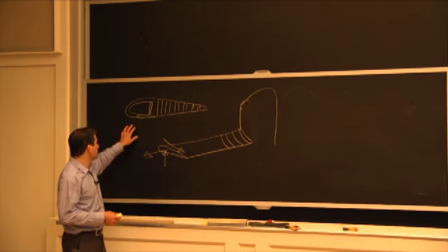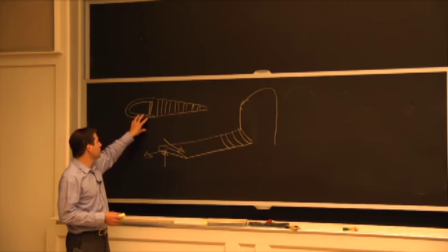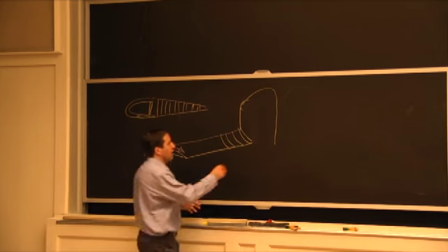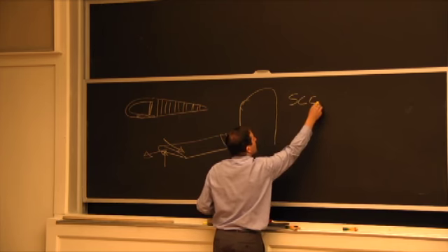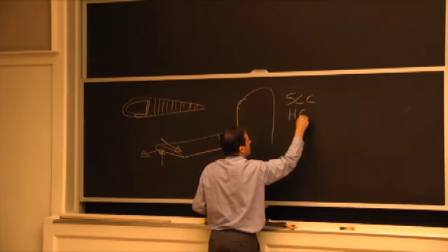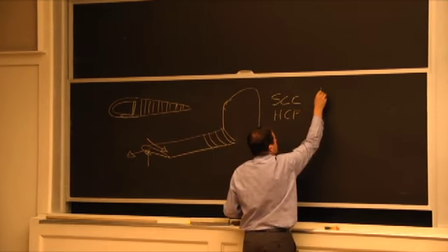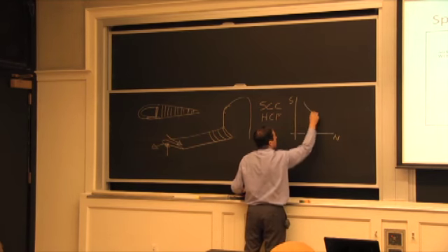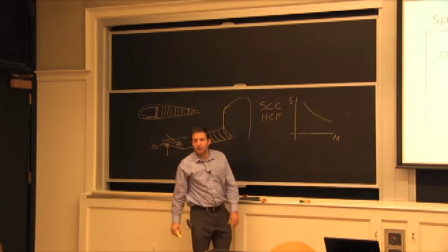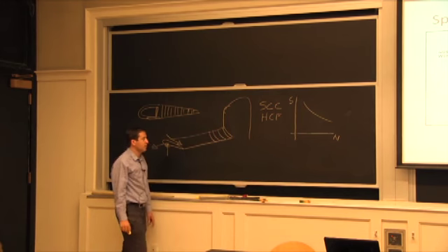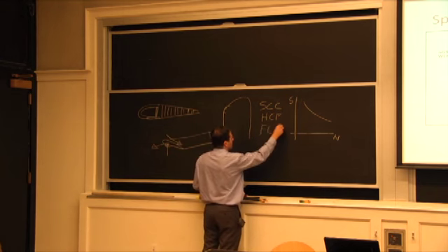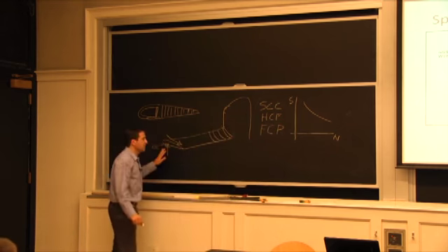So if we have two alloys and we want to verify that the new one is as good, we're looking for stress corrosion cracking. I'm going to look for cycle fatigue, and that's the plot we had yesterday from the SN curve, where over time the strength's going down. So that's also a factor why our safety factor is going down with time. And we may also be looking at fatigue crack propagation. That's the rate by cycle that the crack's going to move if it starts penetrating.